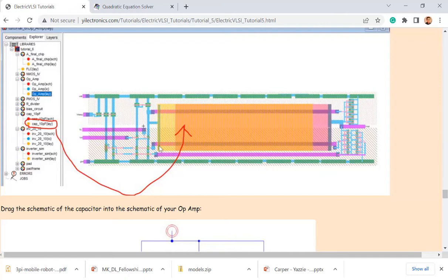All right. Do I have connections to metal 1? Yeah, see? Here's a little wire, metal 1. That's poly 1. The whole line here is a metal 1, poly 1 to metal 1 via, right? Because of that, I can directly connect that via to metal 1. So here's a metal 1 trace. This is one terminal of the cap. What about this one? That's a poly 2 to what? Metal 1. Do I have a metal 1 wire? Yeah, here, right? That's how I make the connections. So those are the 2 terminals of the cap.